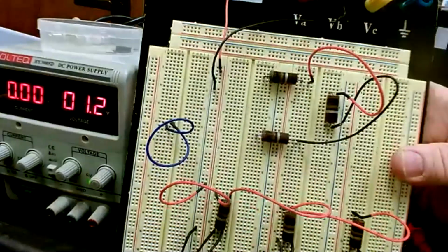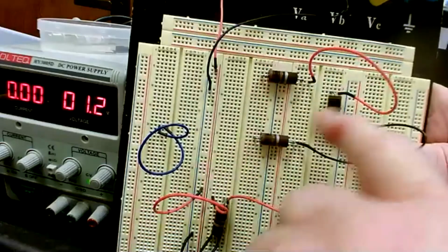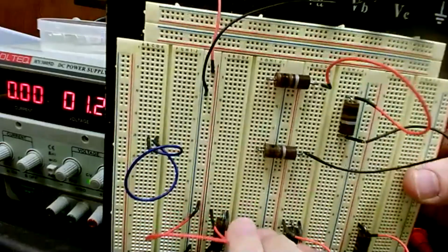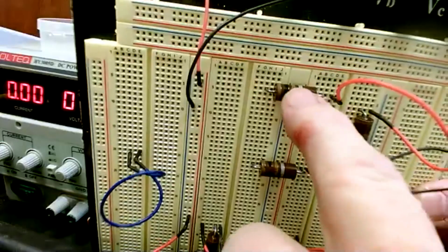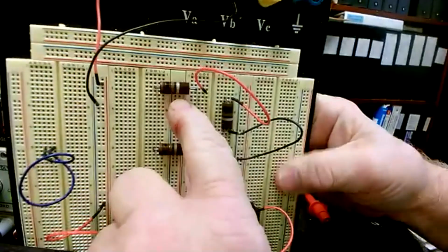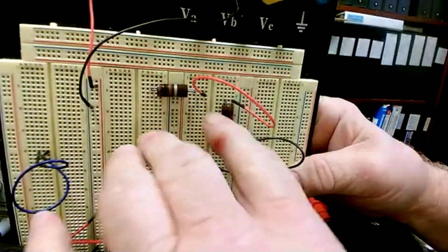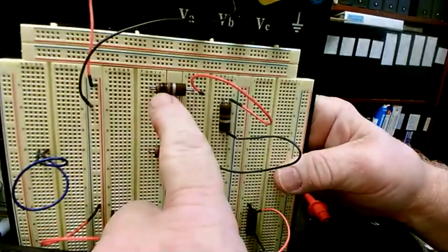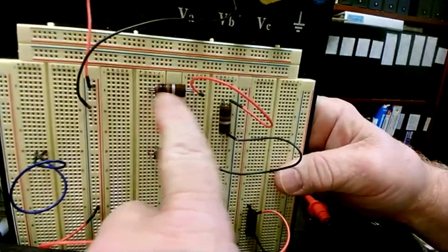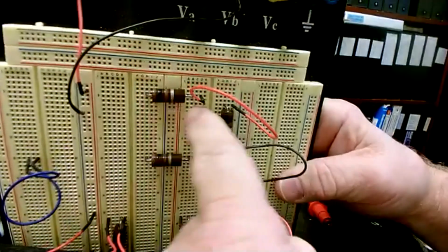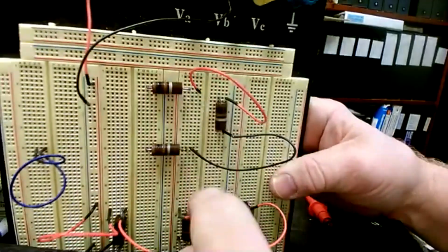Now our series circuit is this. I have 3 resistors in here that are 100 ohms a piece, and I sent you a thing on color code. I just emailed it to you. Now, for the sake of time, I'm not going to explain the colors, but I will talk about it when I see you Tuesday in person, and you can read on it. But those color bands mean 100 ohm, and that silver means it's a tolerance of 10%.